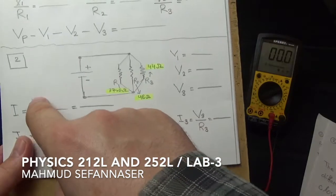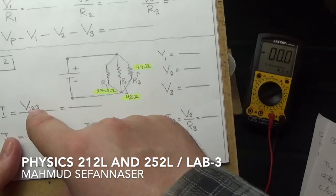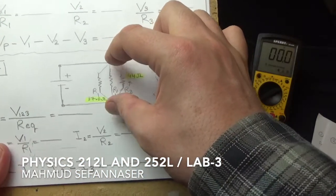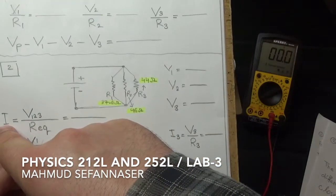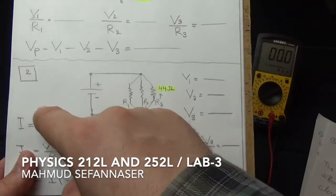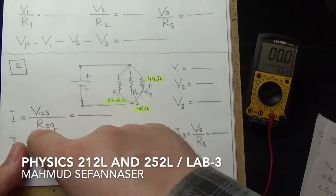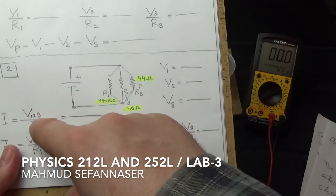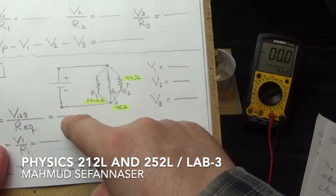And then we are going to figure out V1,2,3, which is the voltage across all of these resistors together. Actually, it is the voltage across the equivalent resistance. And then find the current here, guys. This is the current that flows in the circuit. It's equal to V1,2,3 divided by R equivalent. Actually, when we did the last lab, we evaluated R equivalent. So then we will get the current here.